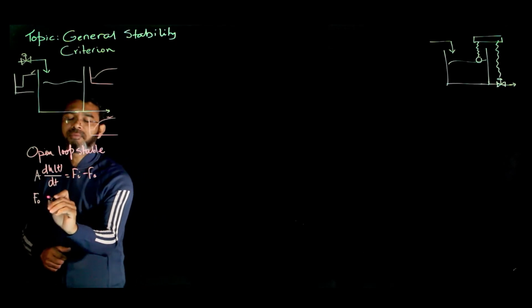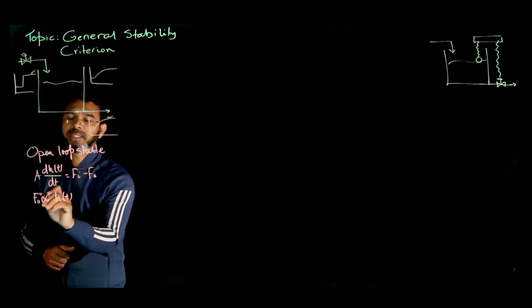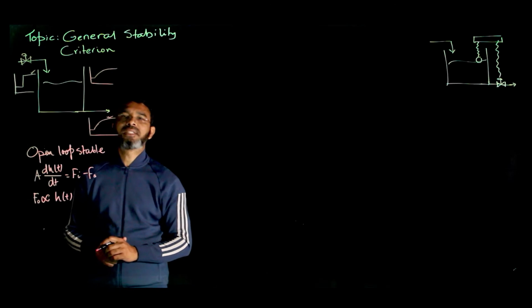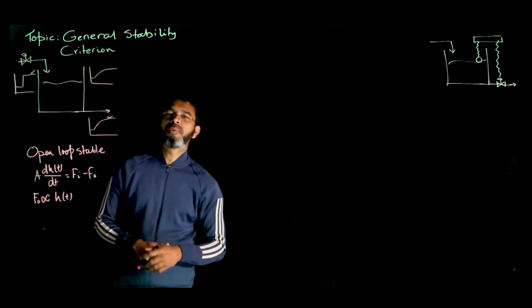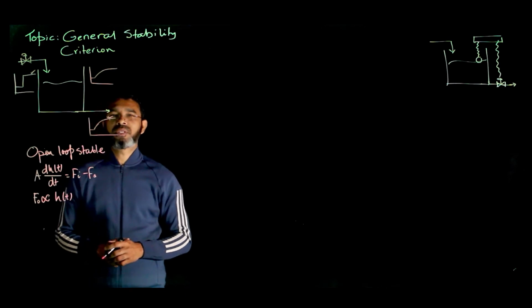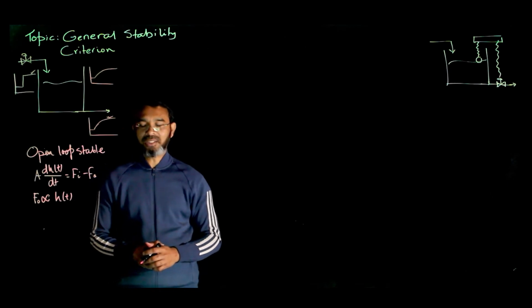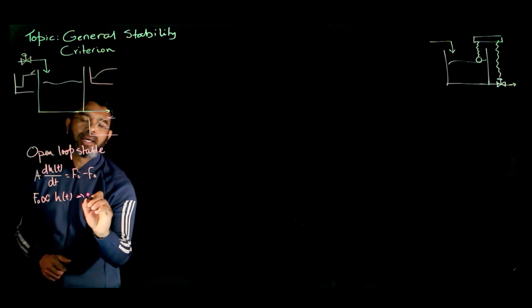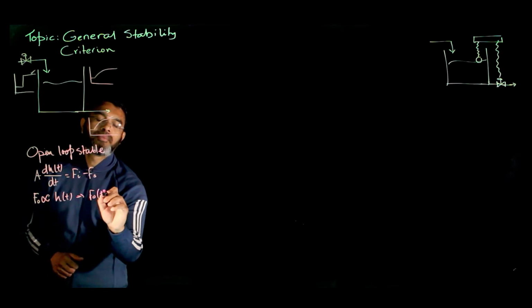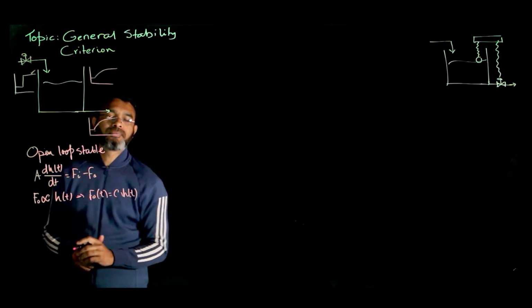So we'll have Fo proportional to, say for the time being, let's assume it's directly proportional to Ht. Now to be correct, it should be the square root of Ht. However, after linearization, you see that it can be written as Fo proportional to Ht. Okay. So then we can write Fo equals some constant times Ht.